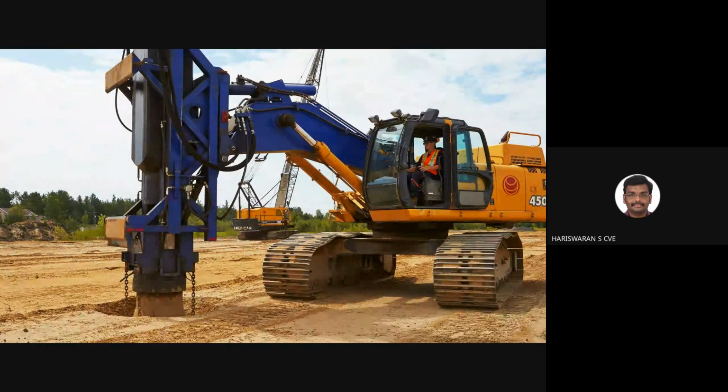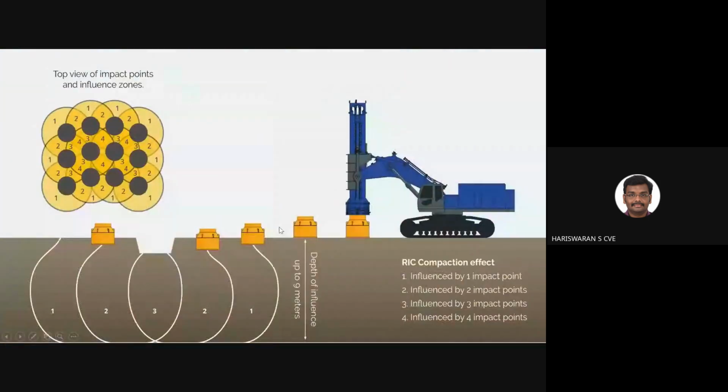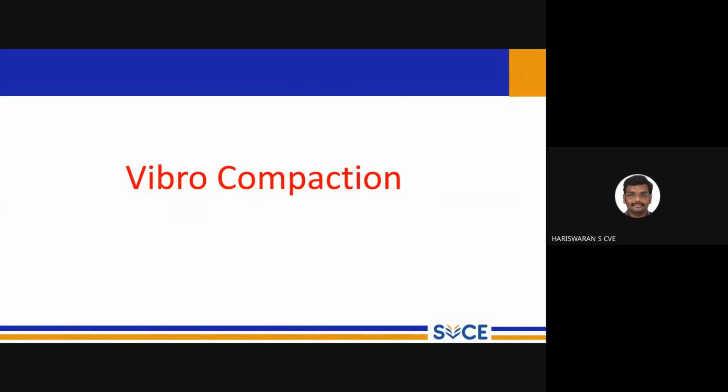But this is recommended for cohesionless soil or slightly cohesive soil, right? Because of this repeated energy, that repeated spacing in and around the region, automatically the surrounding region is going to get compacted. Then that area can be utilized for high-level construction.